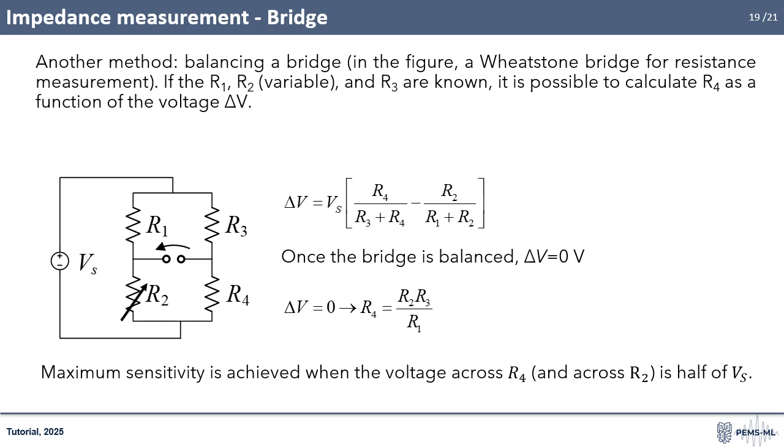Another method which provides an accurate measurement of the impedance is called a measurement bridge. The principle relies on balancing a bridge network, typically the Wheatstone configuration, so that no current flows through the detector branch. When balance is achieved, the ratio of two known impedances equals the ratio involving the unknown one, allowing us to compute its value without requiring a large current through the device under test. Because measurements exist at the balance condition, the system is minimally influenced by loading effects, which improves precision dramatically.